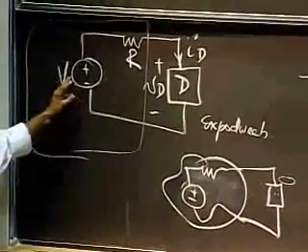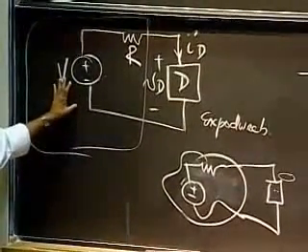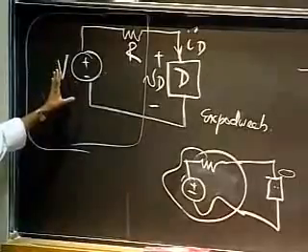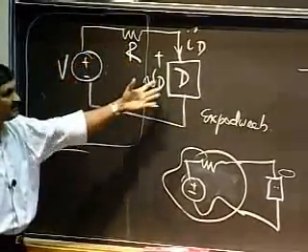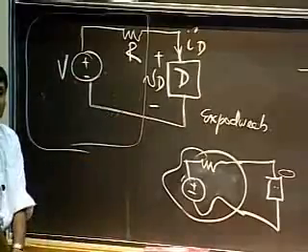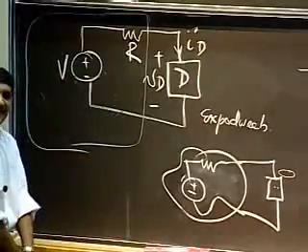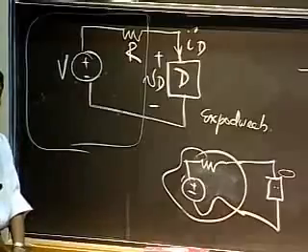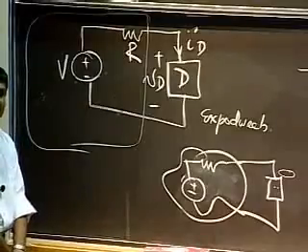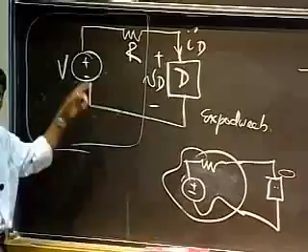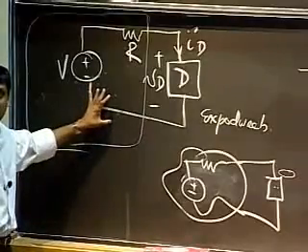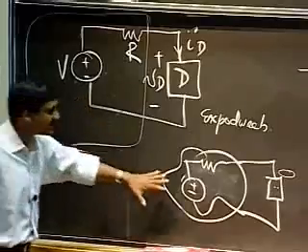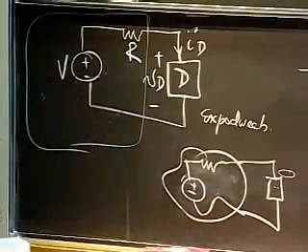What this means is, because of this brilliant Thevenin simplification, going forward through the rest of this course, we'll mostly deal with very simple circuits like this: voltage source, resistor, and a device. That's it. Very, very rarely will you see multiple sources and lots of resistors in a circuit. It's usually going to be simple stuff. And remember how we got here, by making a Thevenin simplification of a linear mess.